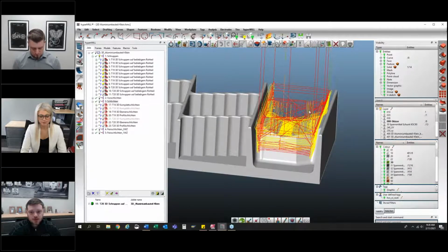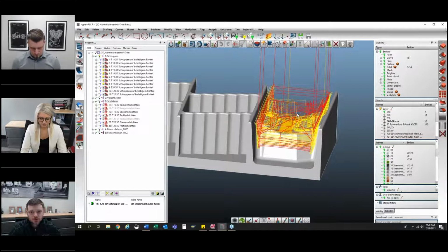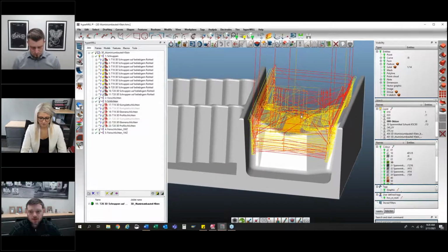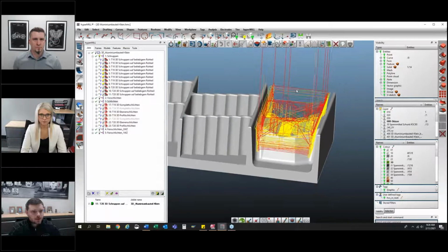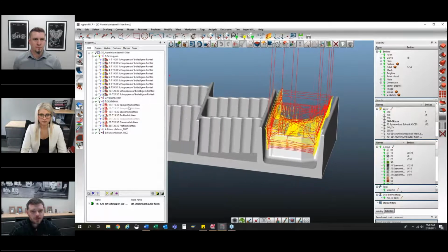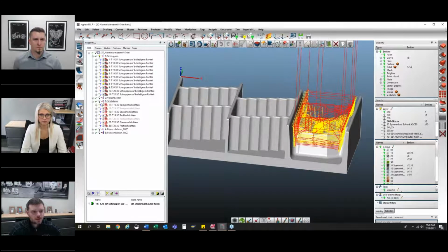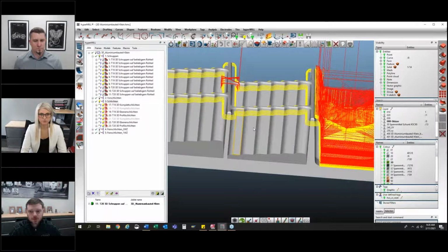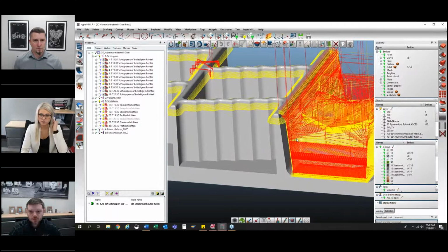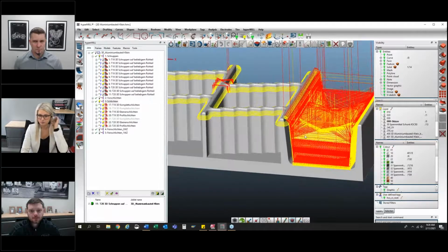So we started off with a true volume mill type path, bottom up roughing, coming through this center slot here, and then working its way up and out. And then the other application that we will show will be a pre-finishing type pass to come in and just knock the extra material off around all these corners and bring these tapered surfaces into size.